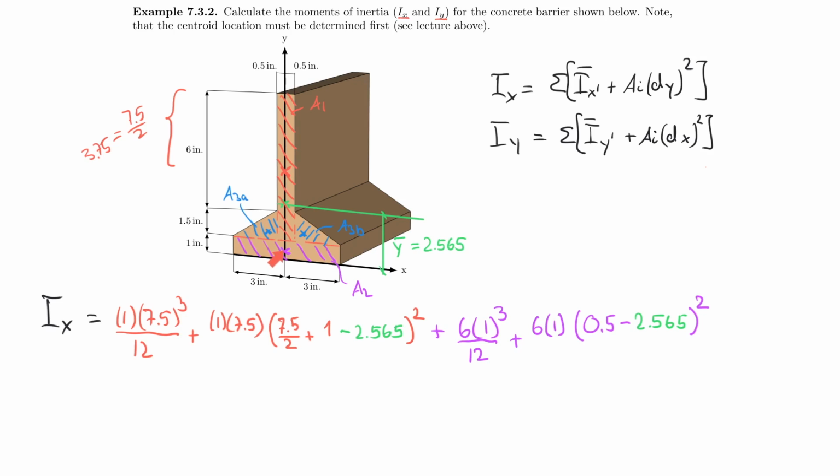I moved from the centroid location down, and then I subtracted this, which is the same as taking the inverse if you don't square it. So like 2.565 minus 0.5. And maybe in this case, it would be very simple to do that. But I want to give you this approach because later on, you may find very complicated structures where you have to add 3, 4, 5 directions or distances to each other and then subtract it. And this method always works. So I would always go from the point that I want down to the reference axis and then subtract that value.